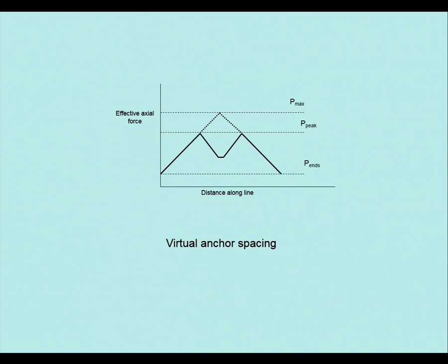So this is your inlet and that's your outlet. Normally, because of the temperature, if this line was long enough, it would expand, stop moving further back. So you've got two virtual anchor points which are overlapping. So there's one in the middle. But what you try to do is make it so it deforms in the middle. And if you allow it to deform, then your force drops off. If your force drops off, it's not likely to buckle.